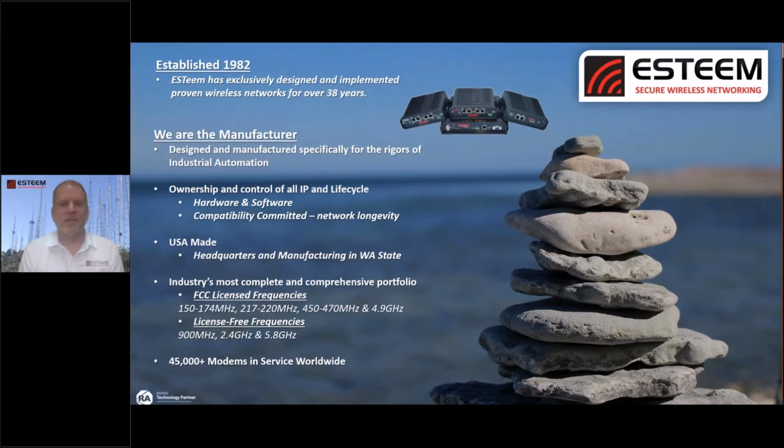We've created 10 different products, probably the most comprehensive portfolio within the industry. We have FCC licensed frequencies, which are your 150 to 174, 217 to 220, 450 to 470, and 4.9 gigahertz. The majority of what we're doing now is the license-free frequencies: 900 megahertz, 2.4 gigahertz, and 5.8 gigahertz. That's the whole brunt of what we're going to be talking about today, those unlicensed frequencies.